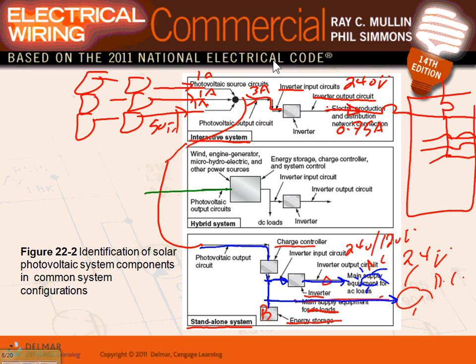Look what the hybrid is. I can have my solar, this is coming from my solar. And I can have wind. Can you guys see wind? Bring the wind in here. I have a generator, bring the generator in here. Can you see how many sources? I have 3-4 sources coming into this system. And I can have an energy storage system, batteries, and a charger or charge controller. Multiple systems basically coming with the solar, with a battery. And out of the whole deal, I can capture it as DC load. I can go feed DC load, or I can invert it back